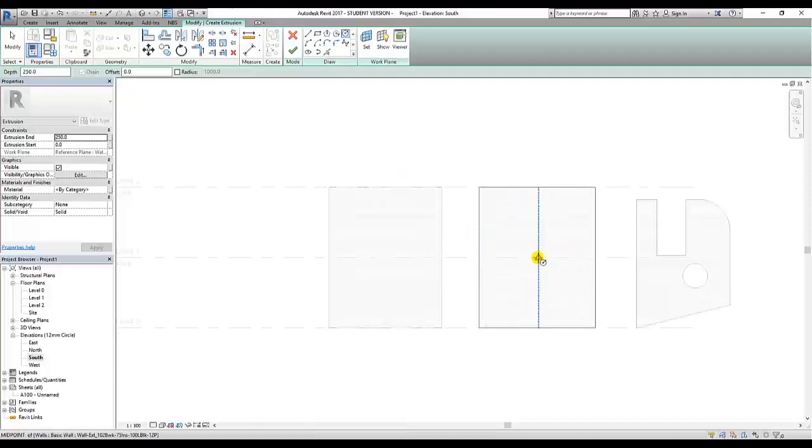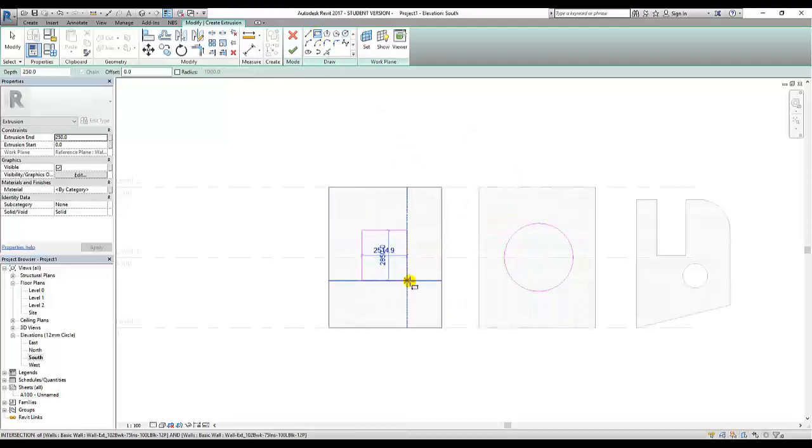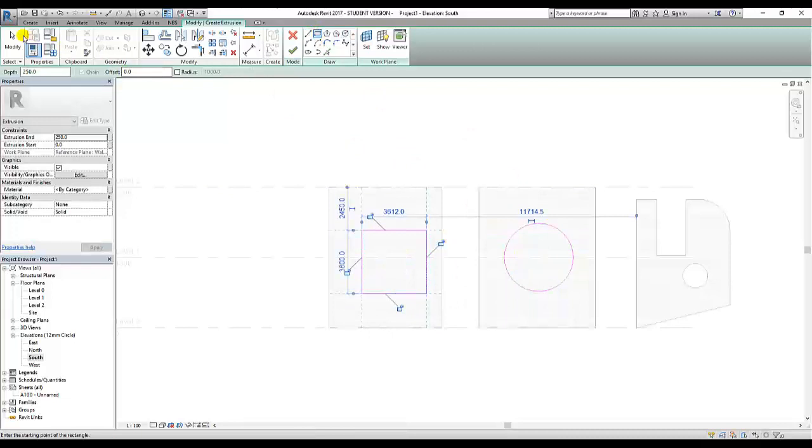And so I shall just choose my position here, create that, and it doesn't have to be round, it can be all sorts of different shapes, and on this one I'll do a rounded rectangle. Okay, so that, and then I'll use the fillet to create those corner shapes. Oops, a daisy. So that's surplus to requirements, and this one, let's do that. Okay, so weird shape, round shape, and you know I don't have to draw them one at a time. I can draw them both together.